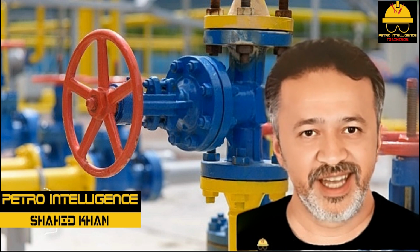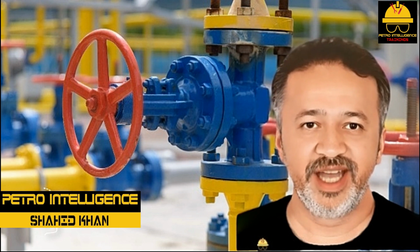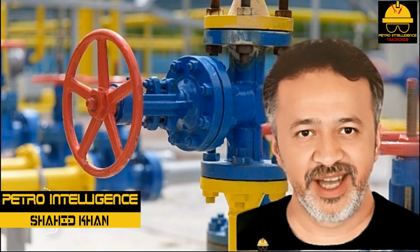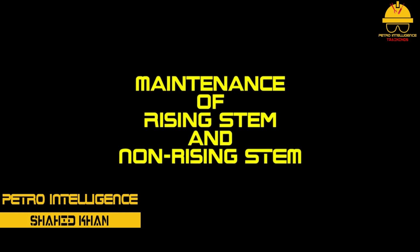The handwheel is attached firmly to the stem of a non-rising gate. Turning the handwheel screws the stem into or out of the gate. You cannot look at this type of valve and tell if it is open or closed.